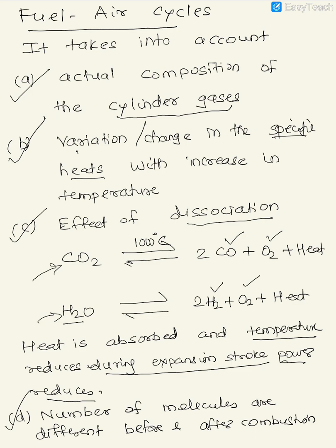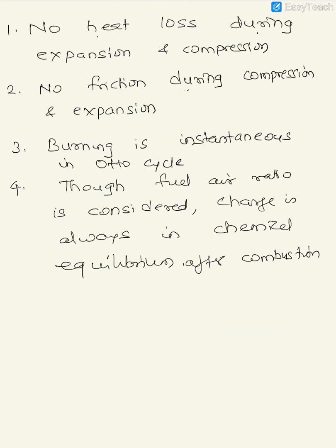Actual cycle analysis is different from fuel air cycle analysis, because in the fuel air cycle analysis, we continue with certain assumptions. Okay, and what are those? The assumption is that there is no heat loss during the expansion stroke and compression stroke. But in reality, in the actual engines, you know that there is a heat loss happening during the expansion and compression stroke. In the real engines, we consider friction. In the fuel air analysis, we do not consider friction.